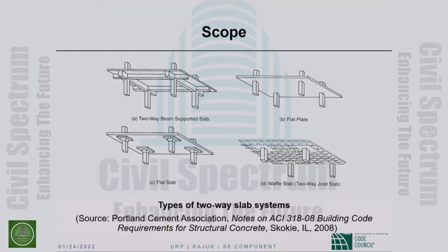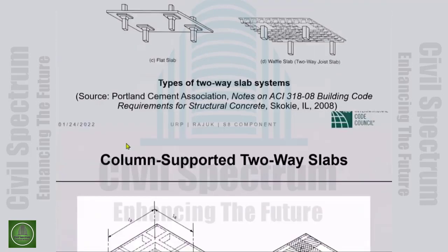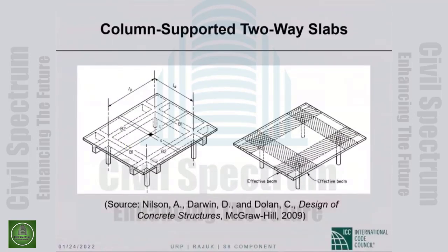Okay. Now it is kind of strange that a flat slab is not flat. A flat plate is flat, but a flat slab has these local thickenings, making it not flat. But that's nomenclature that we have used for a long time. For the same reason of punching shear, the column top is quite often flared, creating what are called column capitals.